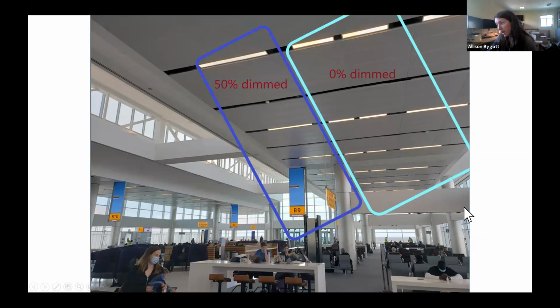And this is the north facade. So we were having a little bit of a problem where the north facade wasn't dimming, even though there was adequate daylight. It just takes some time to calibrate the relationship between the daylight sensor and the amount of daylight that's measured on the work plane. And so you can change that, and that will cause the zone to dim more. Those are important steps, or we don't wind up with daylight control enabled correctly.